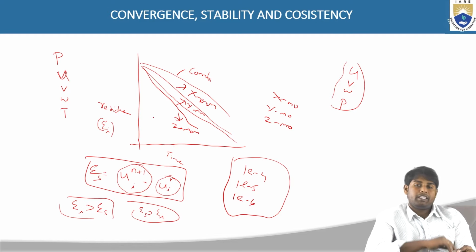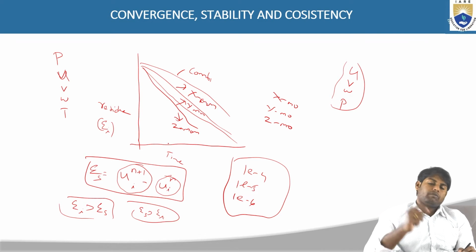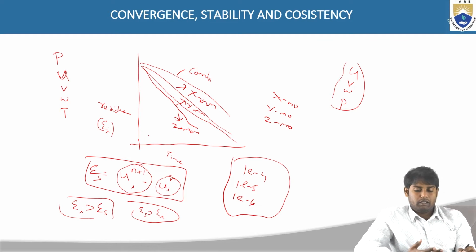Okay, so basically if it is a 3D incompressible flow problem, we have these equations: the continuity equation and the momentum equation. The momentum equation will be of 3, so in total 4 equations. So these are the residues you will be observing. In ANSYS, in the graphic interface, you will be seeing this residue versus time.